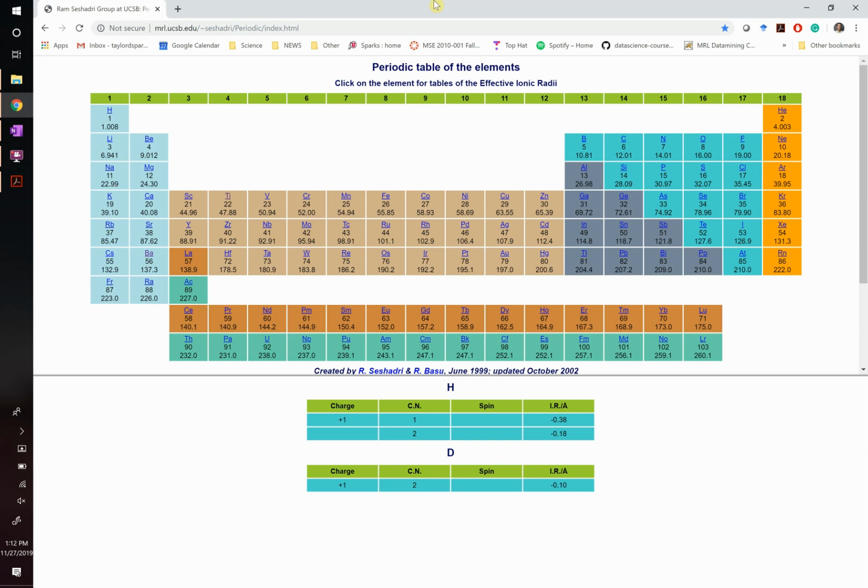If it's going to accept electrons, it better not have more electrons than the gallium and the arsenic. It should have fewer than either the gallium or the arsenic. So for gallium, you could choose something to the left of it. I don't know if zinc is a good P-type dopant in gallium arsenide, but it's not a bad guess, right? One could imagine that it could pick up one more electron and start to look like gallium. Or on the arsenic side, you could put some silicon in. If the silicon chooses to sit on the arsenic site, it might act as an acceptor. This one's a little bit tricky because silicon might sit on the gallium site and act as a donor, and I don't know which one it's going to be, right? But you could guess, okay?